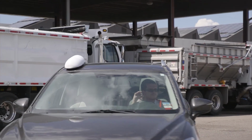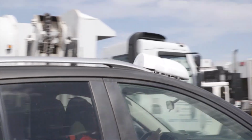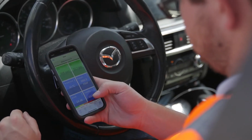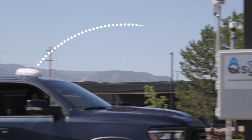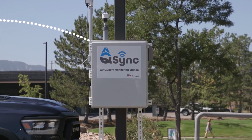I think it's important when you're thinking about low-cost sensors and mobile mapping, how can we keep the data quality high? So through this pilot, we'll be doing, daily, sometimes multiple times during the day, co-locations with these AQSyncs to be able to do calibrations on the fly and make sure the data quality is collected as accurately as possible and updated frequently. Calibrations are accomplished by co-locating a mobile sensor with the AQSync for a short period of time.